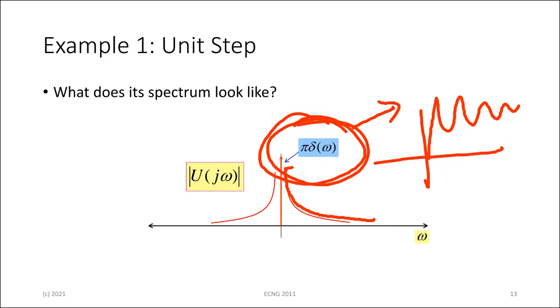But here, we can take a time signal, which in our case is a step, which is off and on. And what is that doing in frequency? If I look at the frequency components, it gives me an impulse at delta 0, at omega equal to 0. So there's a very strong DC signal coming in, which we expect because the unit step has an average value of a half. So there's a DC signal that appears in frequency, and then the magnitude decreases as 1 over omega as you crank up the frequency.